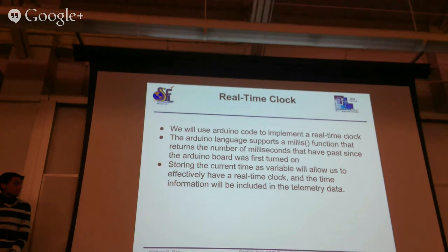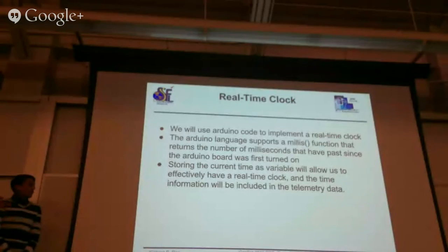Okay, so one of the requirements is to have a real-time clock, and we'll be doing this through our software. The programming language supports the millis function, which returns the number of milliseconds passed since the switch turned on, and this is how we'll be tracking time.